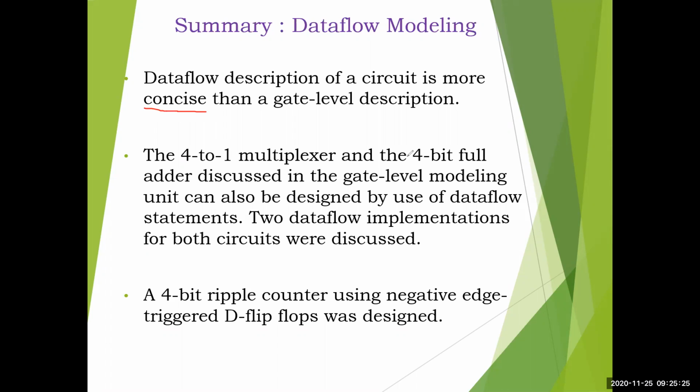The 4:1 multiplexer and the 4-bit full adder, which we discussed in the gate level modeling unit, can also be designed using data flow statements. That is what the first two examples covered. Two data flow implementations of both circuits were discussed: the 4:1 multiplexer using data equations as well as the conditional operator, and the 4-bit full adder using logic equations as well as a carry look ahead adder.